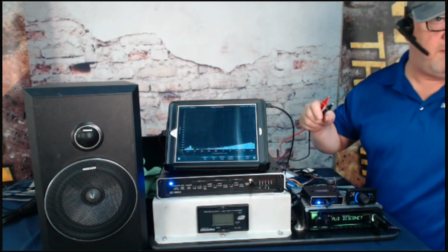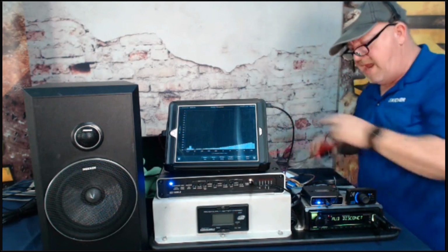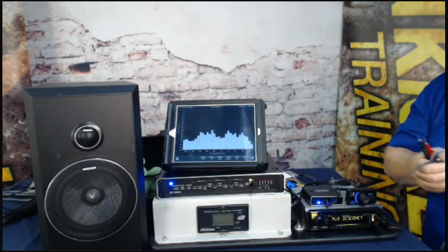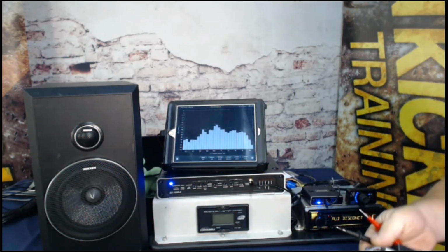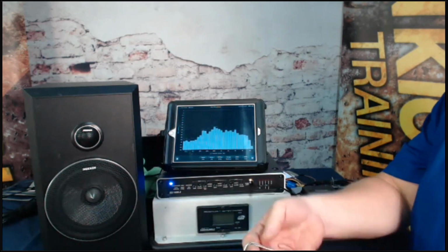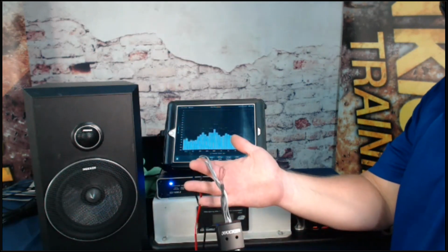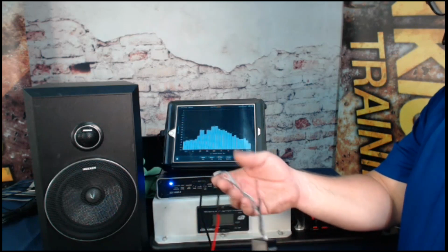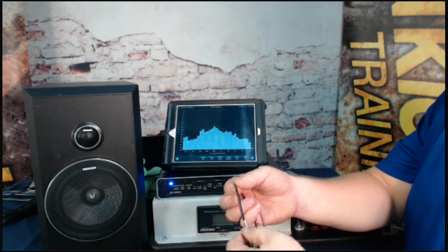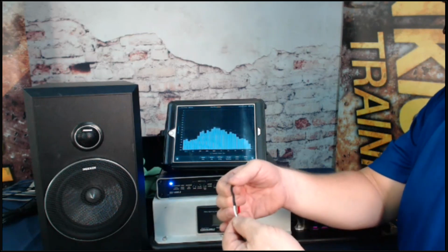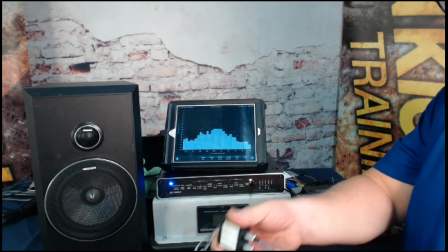To measure the output, we're going to make a little device here, which is actually very simple and very interesting. It consists of a set of test leads, like you'd find on any multimeter. We take that signal and run it into a Kicker KISLOC. This is a line output converter that blocks DC offset. We have separate left and right adjustment. I've taken both negatives and tied them together to the negative lead, both positives tied together to the positive lead. So I've basically monoed out this KISLOC.